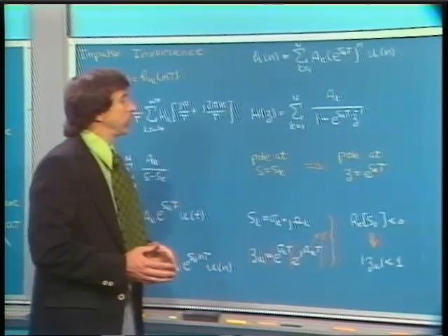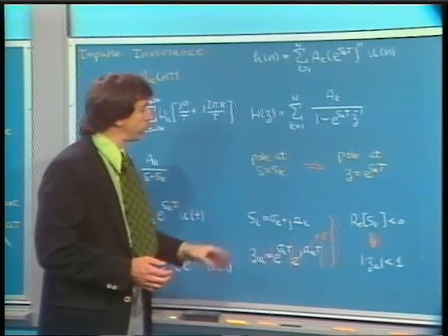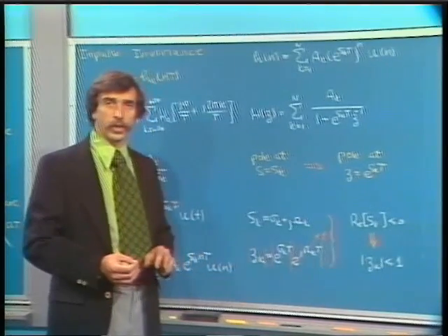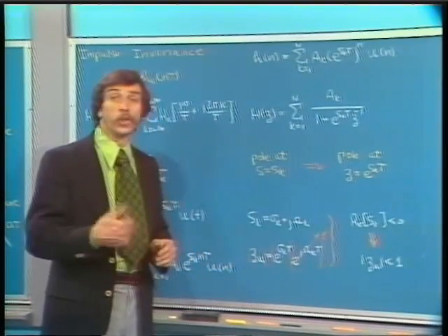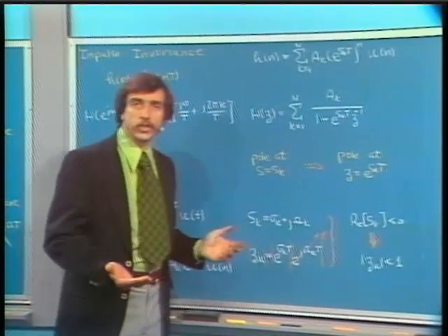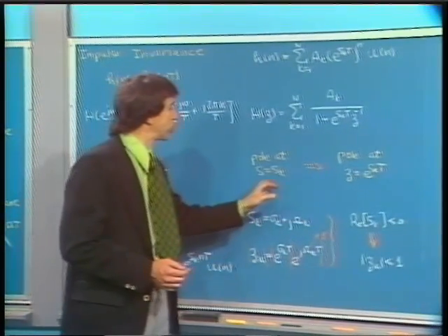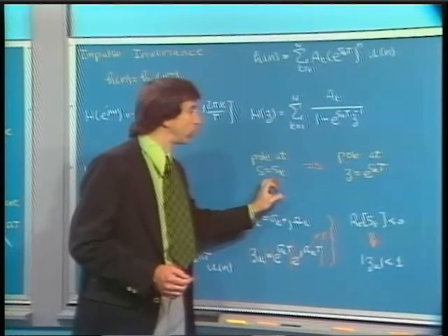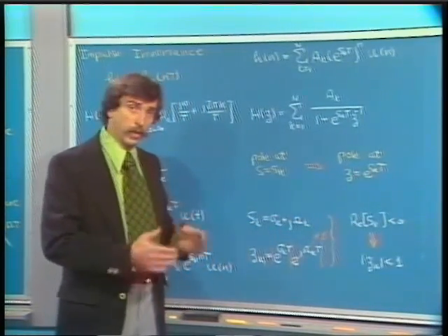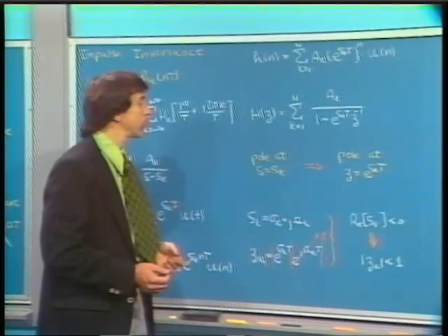In the next lecture, I will briefly present an example of an impulse invariant design, just to remind you of the fact that aliasing is an issue, number one, and number two, that it maps poles according to z equals e to the sT, but not zeros. In fact, the zeros end up someplace else.